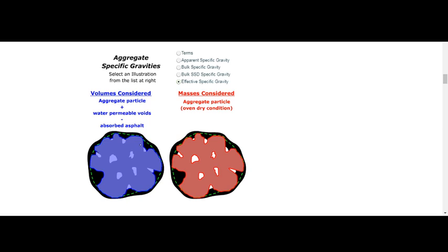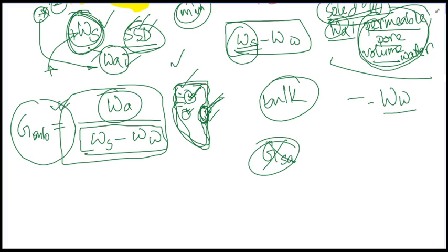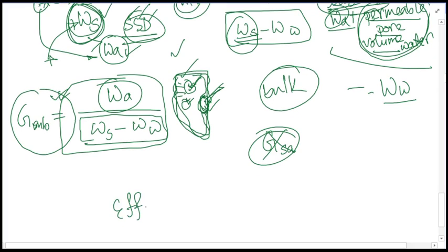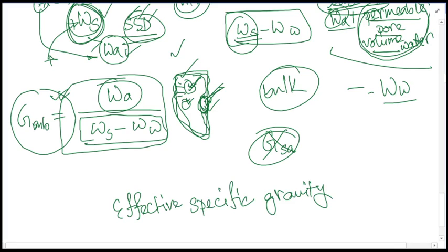And as the absorbed asphalt is totally ignored, we say that this is the effective specific gravity of, not the mixture, rather we use the term, all aggregates.